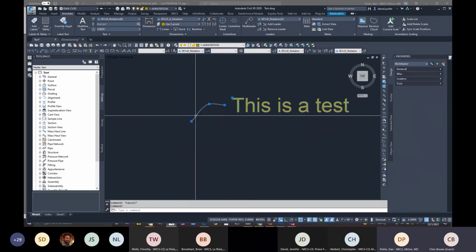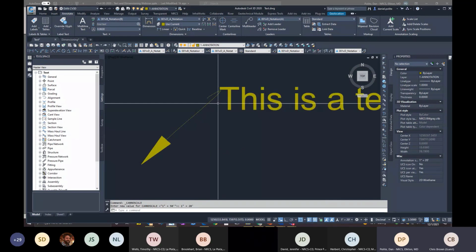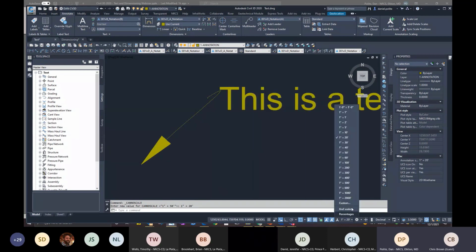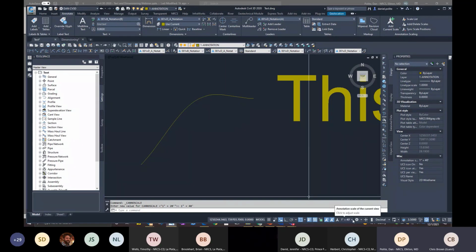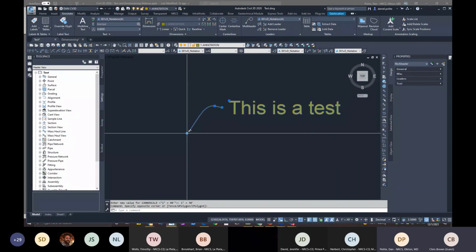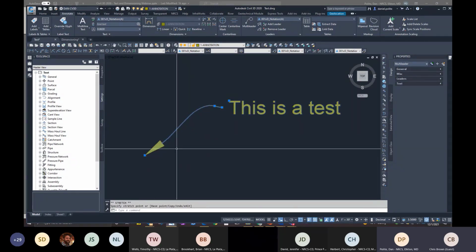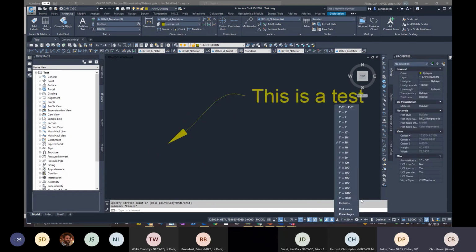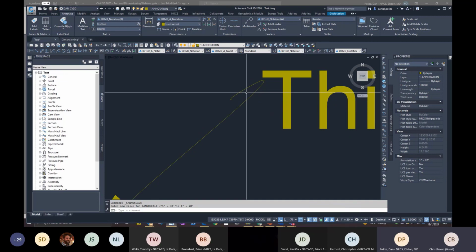But you'll notice on this one, we're at 1 inch equals 50. And then when you start changing scales with the multi-leader, it does get really funny. I will definitely let you know on that, especially with the splines, because you'll notice if you don't make your arrow long or your line long enough, the arrow is not going to show up. If you make it too small, it does some crazy things.